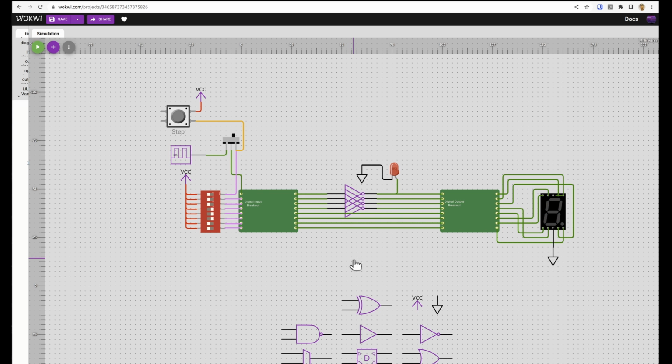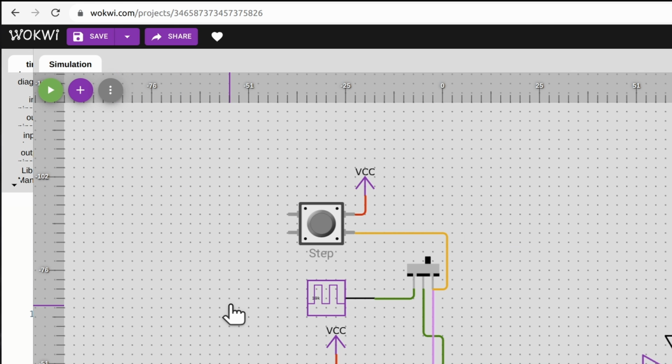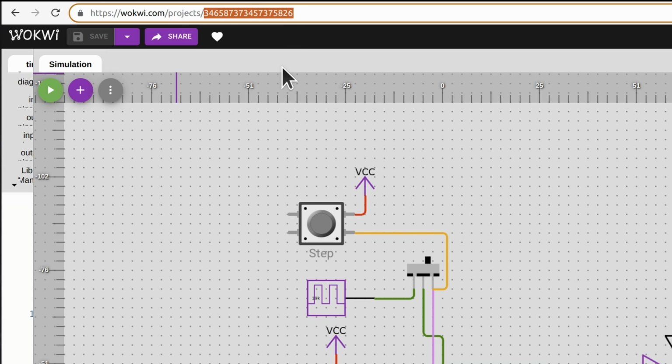Once you're ready to submit your design, you don't need to delete these unconnected things, they'll just be ignored anyway. And another important thing to know is that only the design that is in between the input and the output boards is actually going to get made onto the ASIC. So if you add stuff feeding in here or taking the outputs, that can be useful for testing and simulation, but it won't go onto the chip. After you're finished, you need to remember to press that save button again, and then this number is what you'll be using to make the submission.